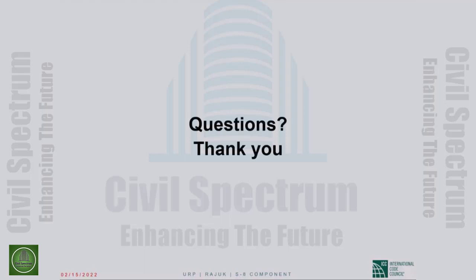So how to calculate the number of required mode shapes, Dr. Ghosh covered in his presentation: participating mass of at least 90%. What is the mass participation impact factor is also covered during his presentation. Which method is better, Newmark beta method or Hilber-Hughes-Taylor method? Hilber-Hughes-Taylor method.